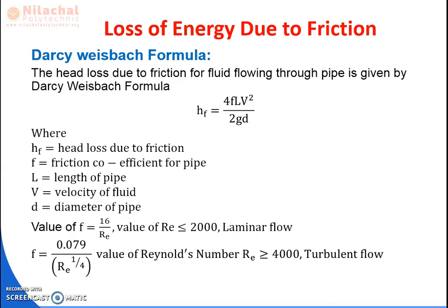The value of the friction coefficient depends upon the type of flow. If the fluid flow is laminar, then we use the value of f as 16 by Re.